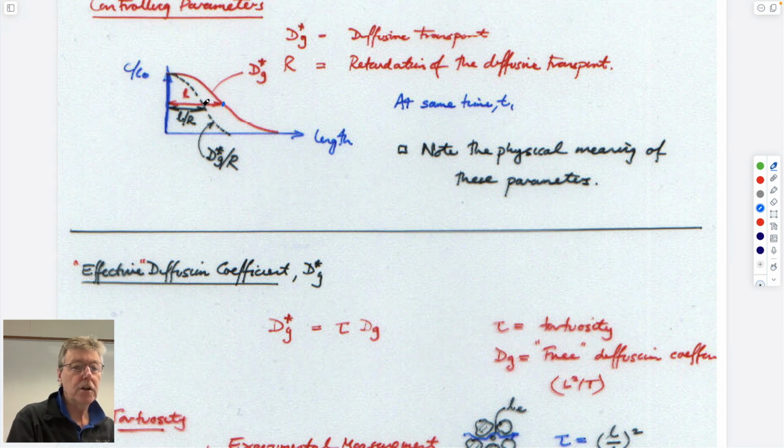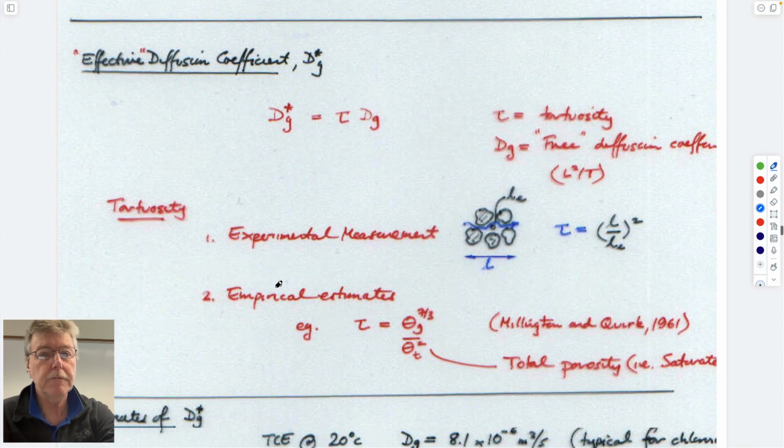If it's non-conservative and it's being sorbed onto the water and the substrate, then it would travel less far in that time. And you could calculate based on the equations we used, but using an effective diffusion coefficient, which is just reduced by a factor of 1 over r. So that's physically what the retardation coefficient would mean, although we haven't really said what Rg would be yet. So let's save that excitement for the future.